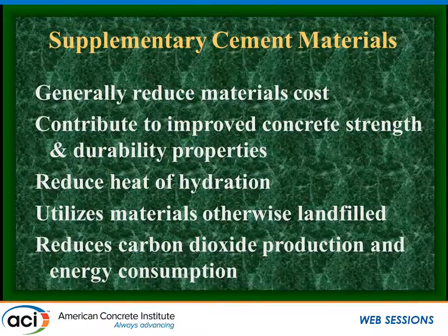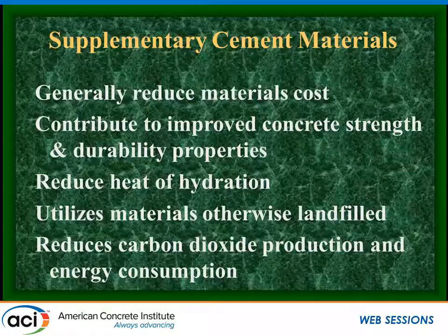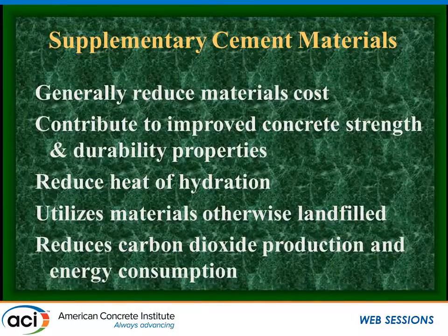And then the third impetus for the use of these materials is the environmental, the sustainability angle. We're utilizing materials that would otherwise be landfilled. We're reducing carbon dioxide production and energy consumption when we use these materials as a partial replacement for Portland. The energy that's embodied in these supplementary cement materials is already expended in the primary process that they were derived from. So for every ton of supplementary cement material, we're saving a ton of Portland, we're saving a ton of CO2 emissions, we're saving an awful lot of energy consumption by using these materials.